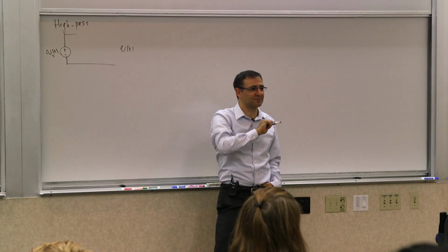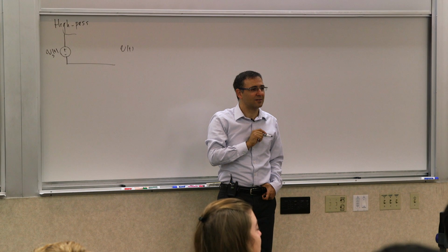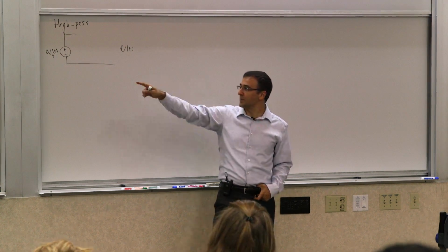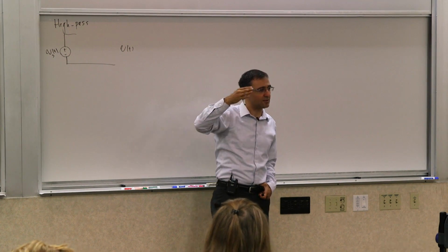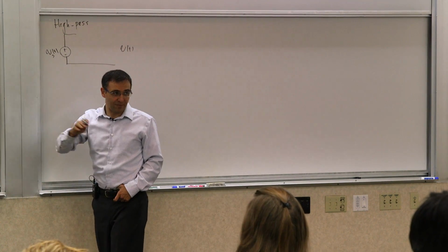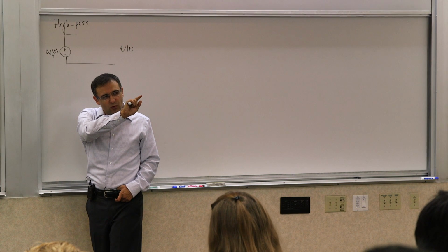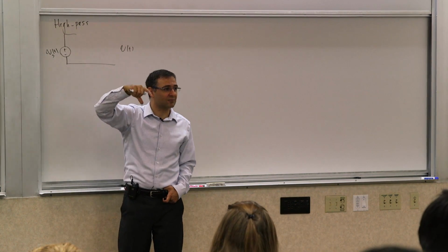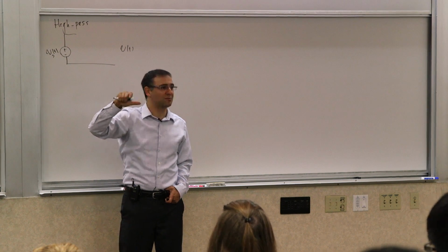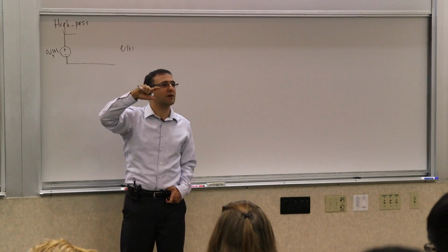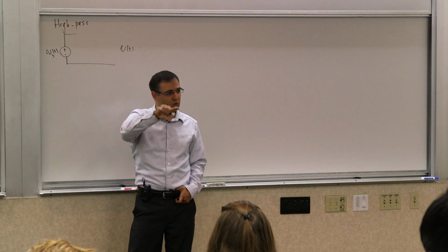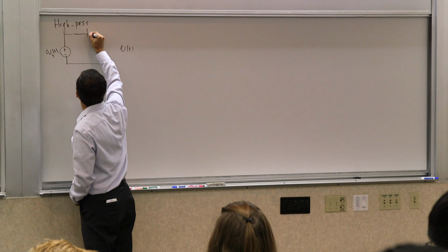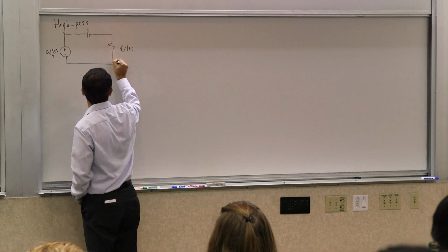Okay. So, yes? Just swap the locations, like just measure the voltage across the resistor. Or basically swap the capacitor and resistor, right? If I want to draw it in the same format. What you said is exactly true, with one caveat, except for the fact that you need to be looking at the voltage across the resistor. Your ground would be at a different place. If you want to measure a voltage with respect to ground, then you need to switch them. But you're right, the voltage across the resistor will have that behavior. So I can put the capacitor here and the resistor here.